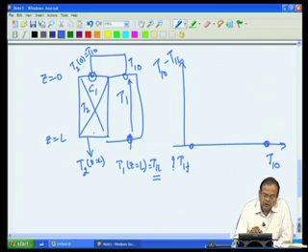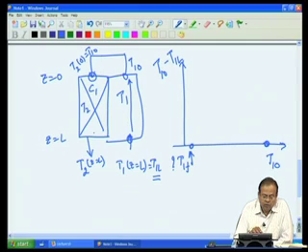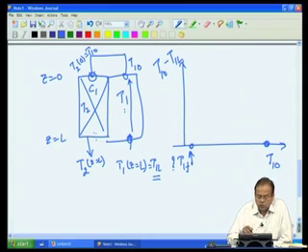Namely, if temperature T10 is low, then the extent of reaction will be very low, because the rate constants are low. Hence, there will not be hardly any difference in condition from the z equal to 0 to z equal to L, or in other words hardly any reaction in the reactor, therefore, hardly energy transfer from the reactor to the reactant, and therefore, hardly any increase in temperature from T1L to T10. So, we will have a point somewhere like this, where T10 is pretty much close to T1L.